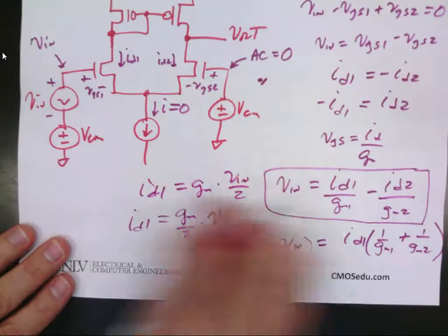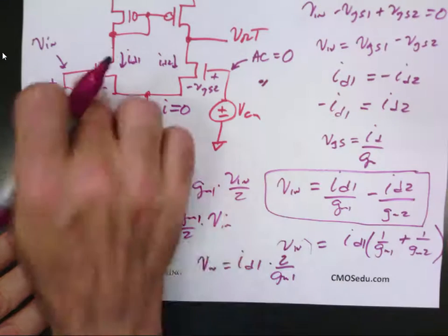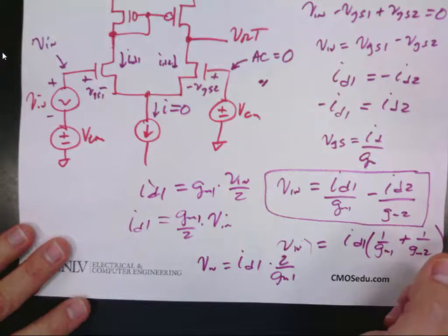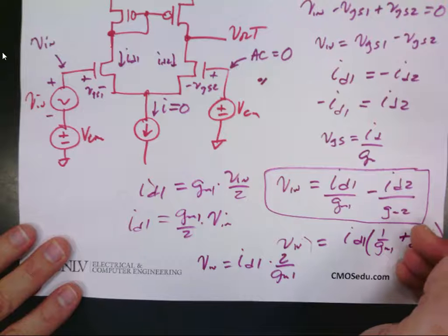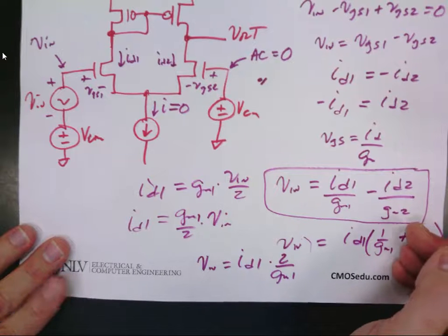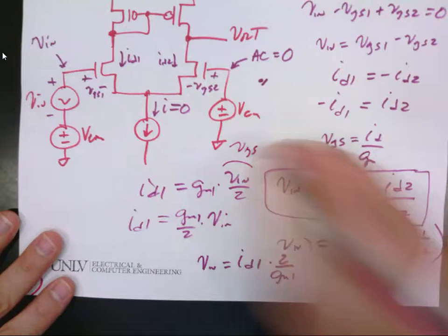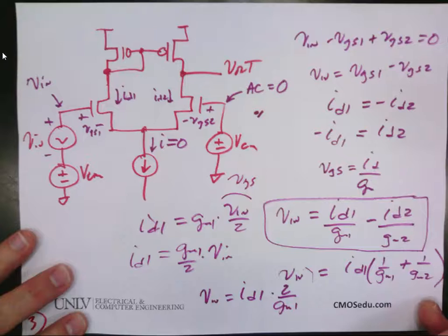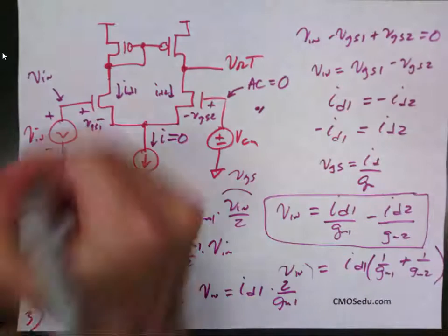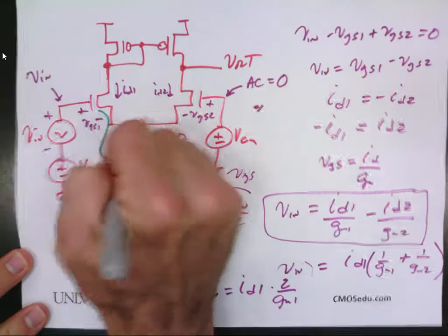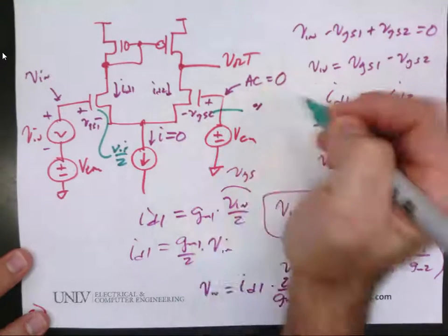How is this relation, and we could put 1 here if you wanted, how is this relation related to the transistor's VGS? Vn over 2 is equal to VGS. Does everybody agree with that? So if I ask, what's this voltage here? We just showed it's Vn over 2. Similarly, what is this voltage?